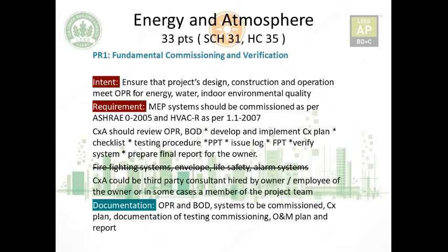To remember, firefighting system, building envelope, life safety and alarm systems are not part of this fundamental commissioning and verification prerequisite. For the documentation, OPR and BOD should be submitted, the systems you are commissioning should be submitted, and the commissioning plan based on which you will be commissioning, and documentation of testing and commissioning, the final documentation that you made, the O&M or operation and maintenance plan, and the final report.